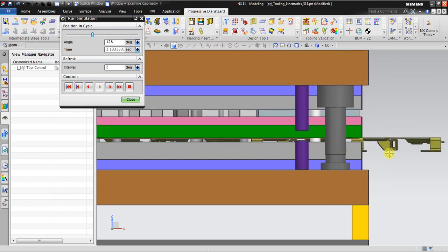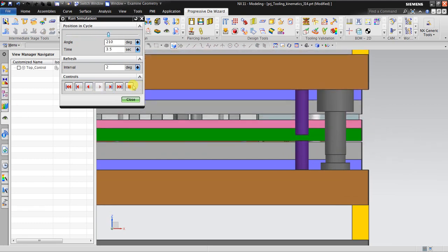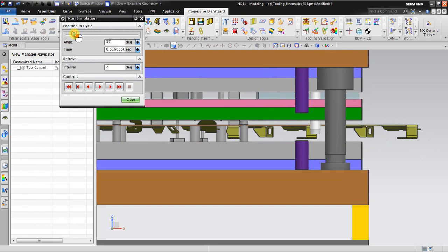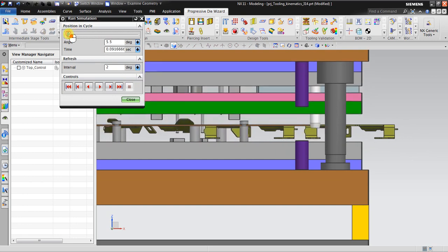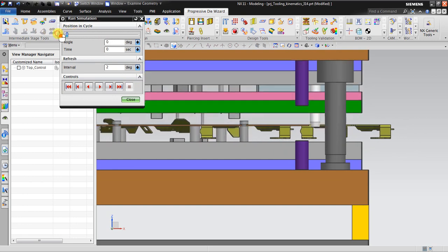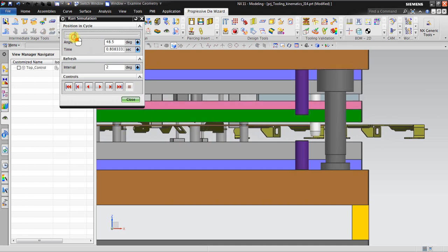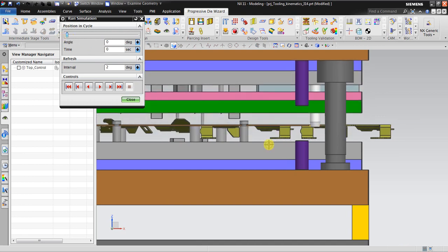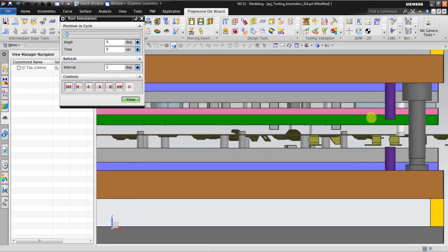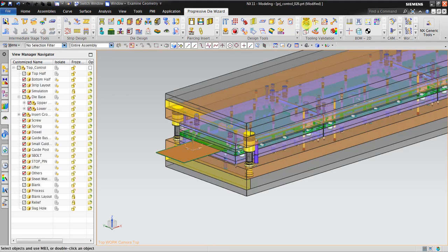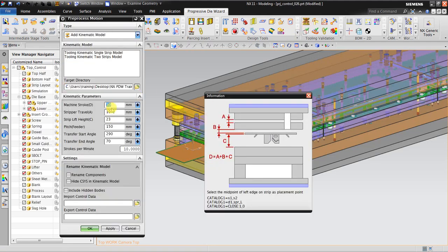You can see. Okay, understand. Stop. Okay, it's lifting here. But you can see now when it moves, this will start touching, so there's going to be interference. So it means the lifting of 50 millimeters is too small. Going back again, maybe about machine stroke about 80.